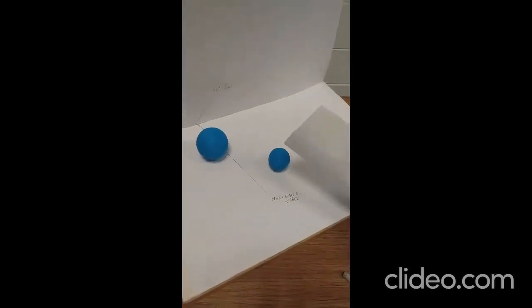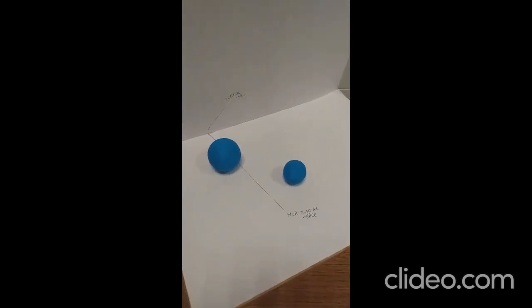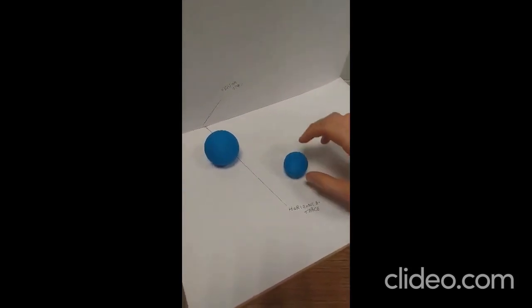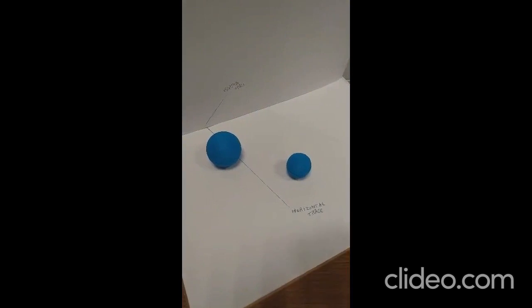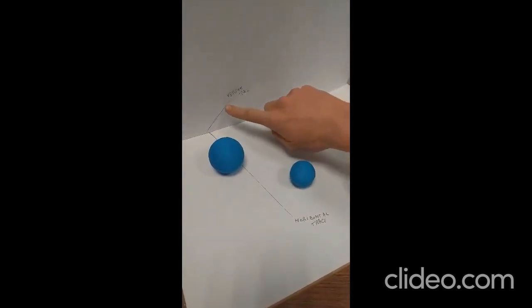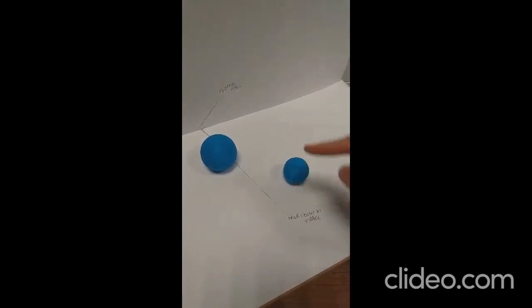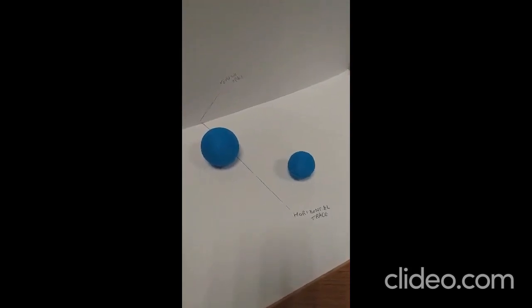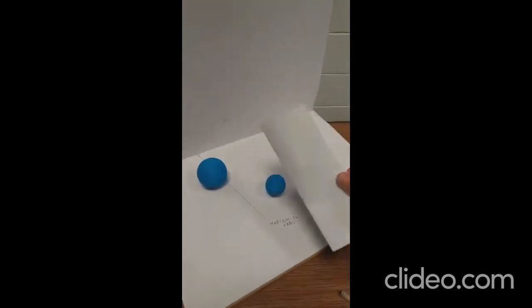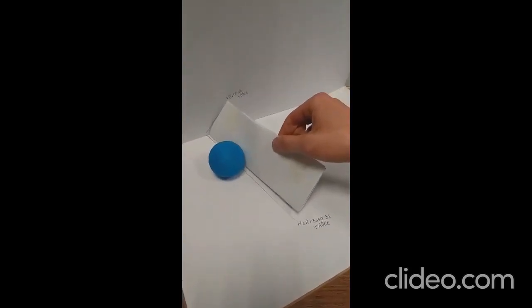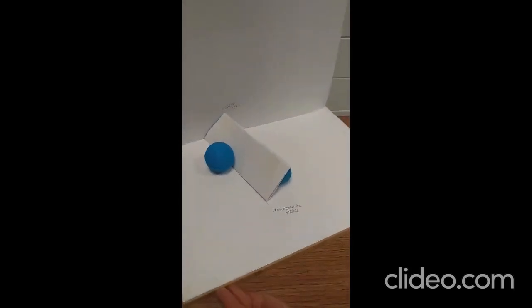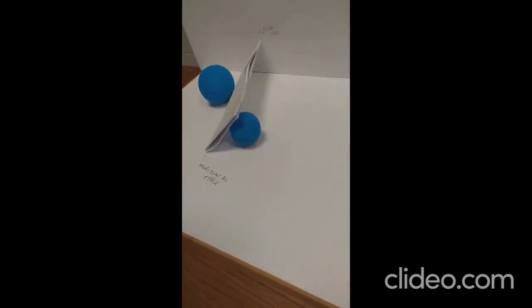Using a 3D model, we can allow students to show at the top of the class a visual representation of this problem. We've already made on the 3D printer our small sphere and our bigger sphere. First of all, on our solution, we will have our vertical trace and our horizontal trace. This here, horizontal trace, is where we'll position our internal tangent plane. So if we get our plane, we'll do something simple here now, place it in between, just as a visual representation for the students, along our vertical trace, then our horizontal trace. This is a great aid for students to show them exactly the solution to this problem.